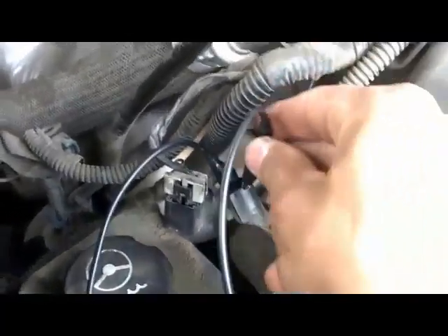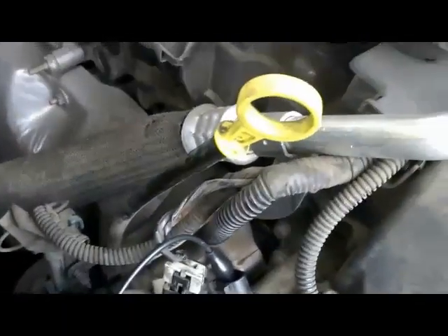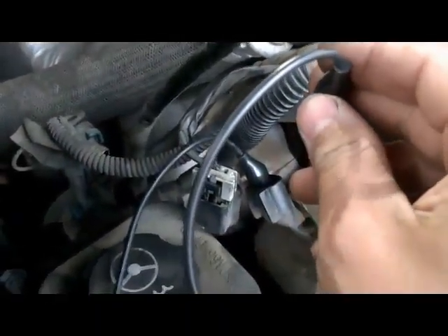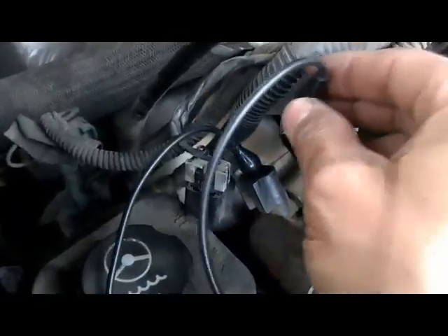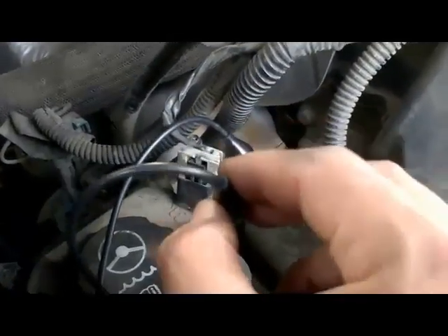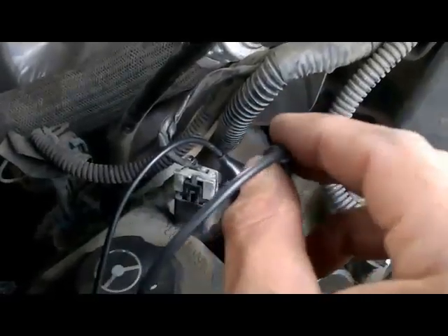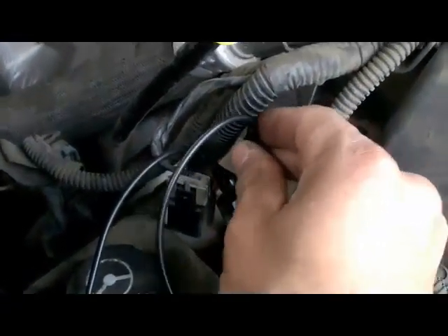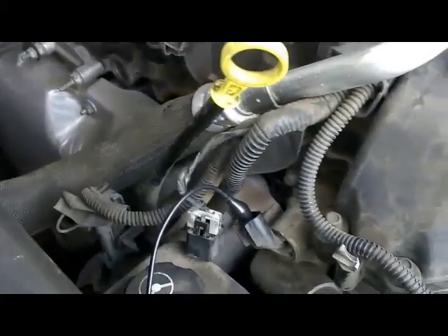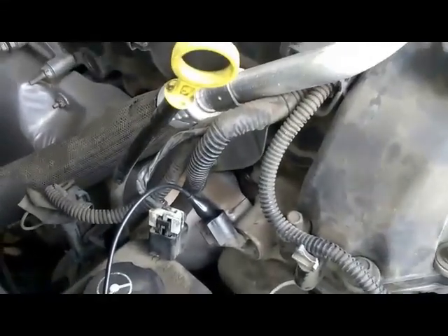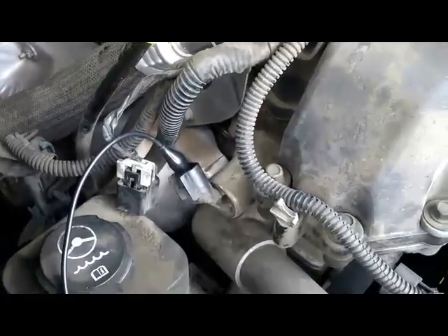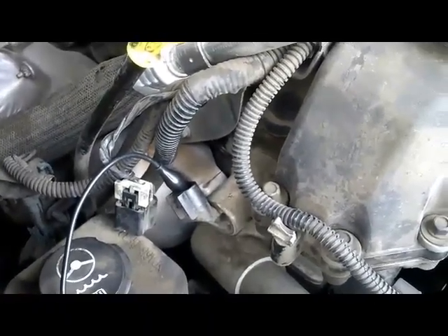I'm going to perform this manual solenoid function here, and let's watch our engine either run real rough or even stall. So here we go. As you can see, our engine almost stalled. I'm going to perform this one more time. You can see in our second try, our engine did stall. So if this symptom happens, it means that our solenoid is functioning. It has no opens or shorts. It is performing what it's supposed to do.